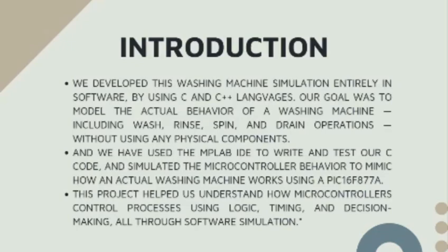And we have used the MPLAB IDE to write and test our C code and simulated the microcontroller behavior to mimic how an actual washing machine works using a PIC16F877A. This project helps us to understand how microcontrollers process using logic, timing and decision making, all through software simulation.